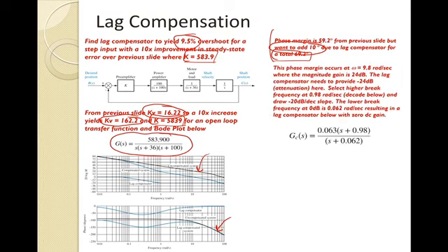Okay. So this phase margin, if I look at my uncompensated system, 69, so 180 minus 69, so that's about 70. So that's going to be about 110, and that's going to be just right about there. And that's just under about 10 radians per second. So here I'm saying it's about 9.8 radians per second.